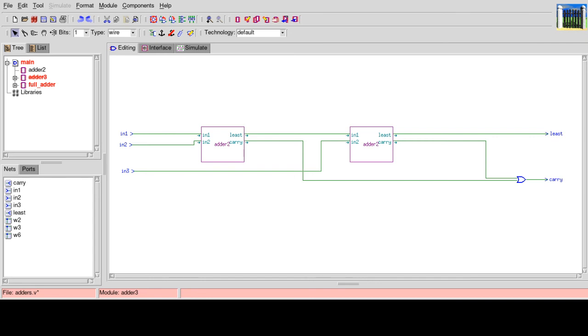You say, but it doesn't look like it, only because inside of these boxes here, those boxes represent 2-bit adders. Okay, and inside of the boxes are the AND and the exclusive OR gate. So each one of those boxes has an AND and an exclusive OR gate. Okay, they're basically two 2-bit adders. So two 2-bit adders plus this OR gate right here gives you a 3-bit adder.